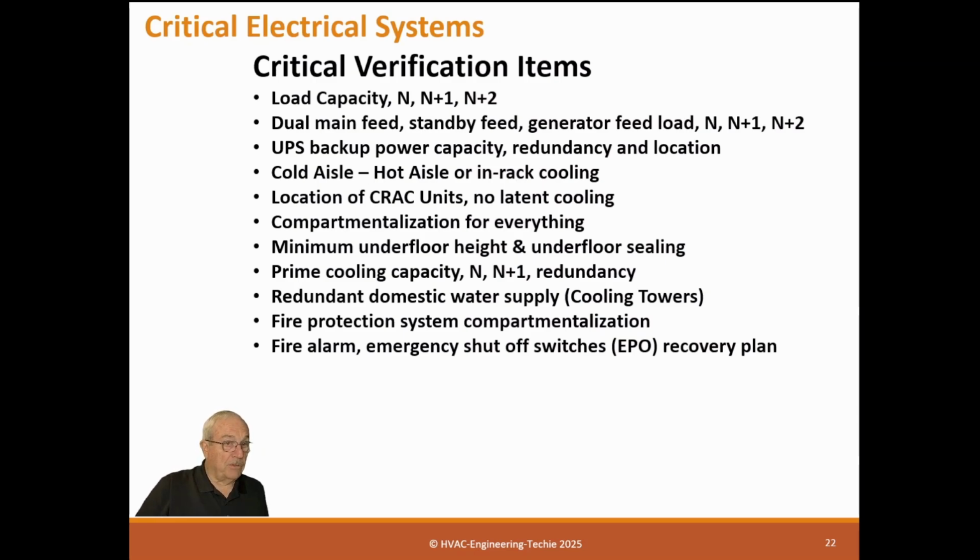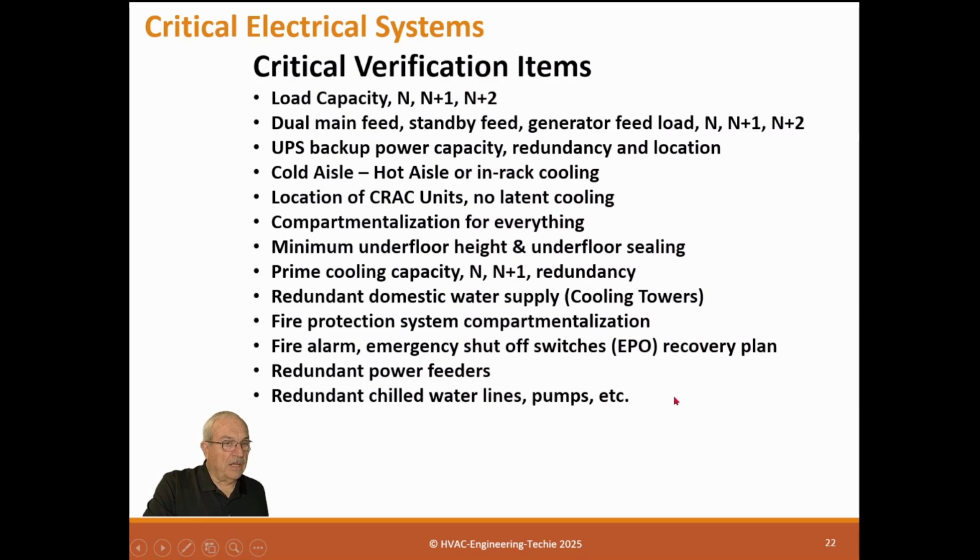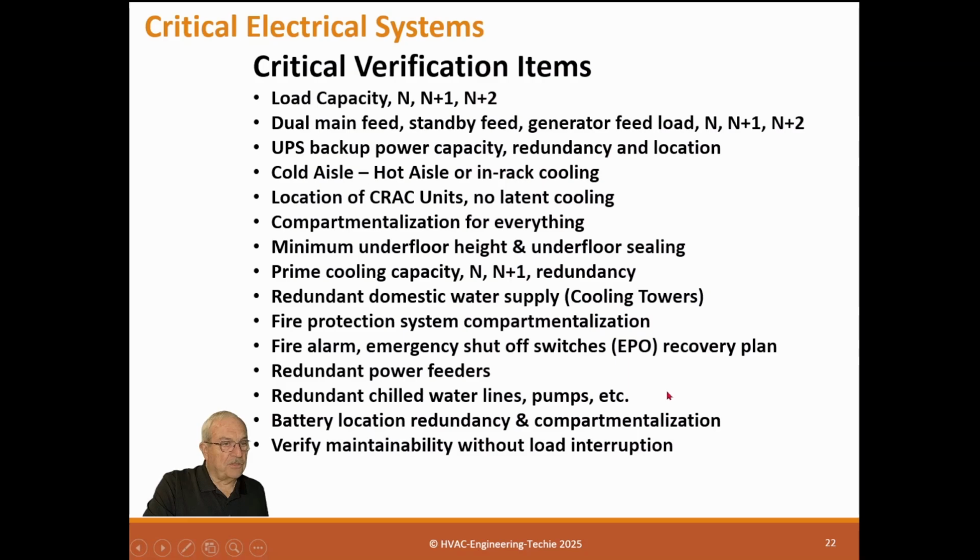An EPO is an emergency turn-off switch. If you hit it, you turn off the systems. But what's critical is how you recover from that EPO event. It's not a simple matter to get everything back online or restart it after an EPO, so we need to have a recovery plan for that. That's really important. Redundant power feeds, redundant chilled water lines, pumps, etc. Battery location, redundancy, and compartmentalization.